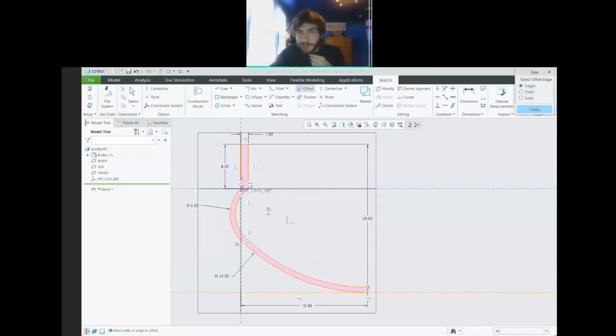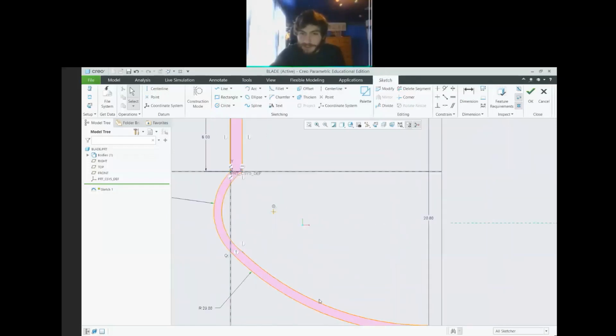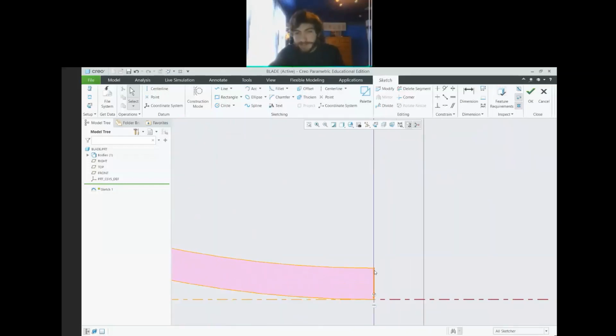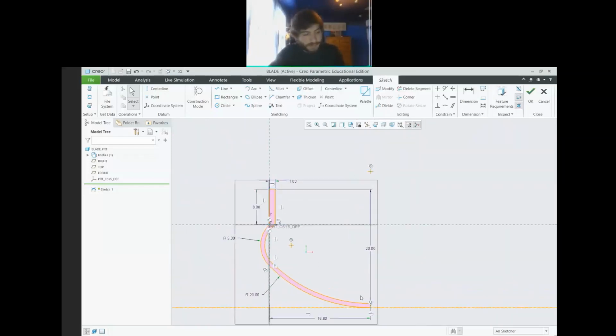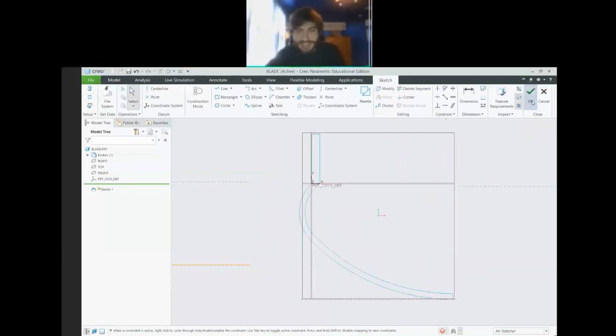And then when that created a smaller version of our arc, we used the coincident constraint, and we took one end of it and attached it to our free hanging vertical line over here, just so we can get one continuous shape. We did the same thing for this bottom arc. We connected it to the end here, and then drew a vertical line to connect these 2 points. We'll press the big green check mark, which says we are done with this sketch.